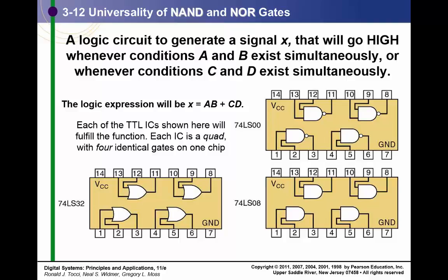These are the chips that we typically use. These are 74XX family. 74LS means low power, high speed. The LS is the family, and the 00 is the functionality. 74 means it's basic logic. You'll sometimes see 54, which is a little bit different. 74 applies to transistor-transistor logic, or TTL.